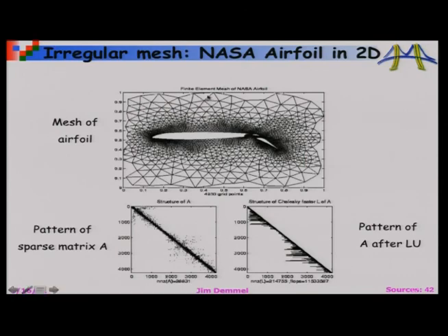So these are little finite elements. Each one is connected to its neighbors. And you write down a system of equations, and the connectivity here tells you what the sparse matrix looks like. And if you write it down as a matrix, this is what's called its spy plot. Every little black dot is a non-zero. And if you put things in a reasonable order, everybody is only talking to its nearest neighbors.